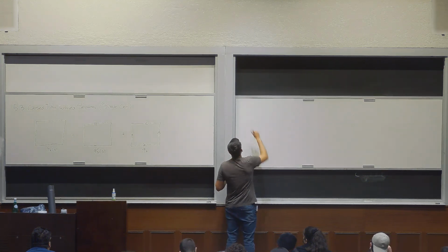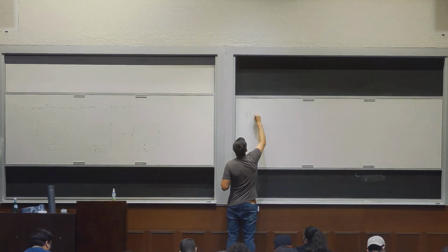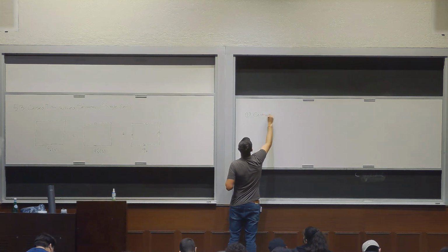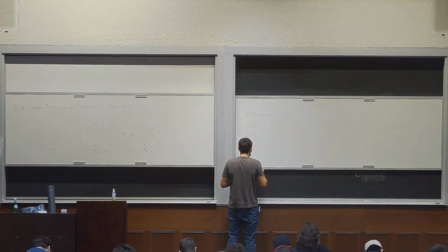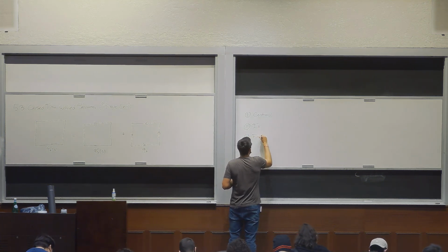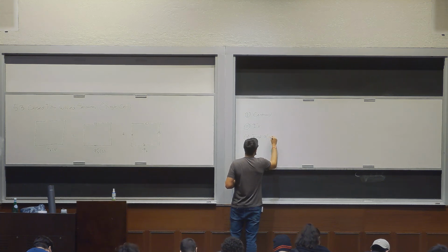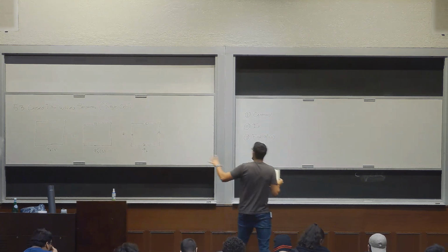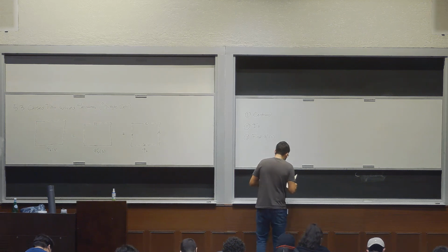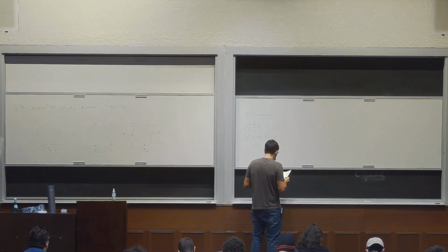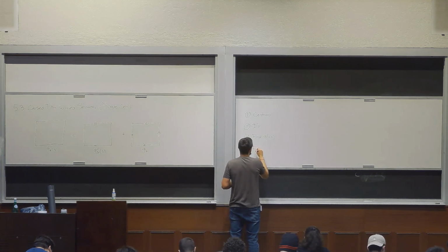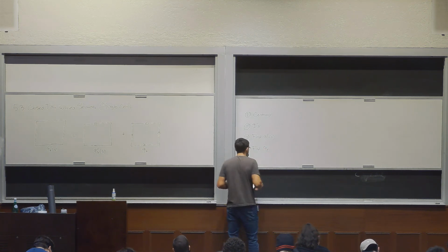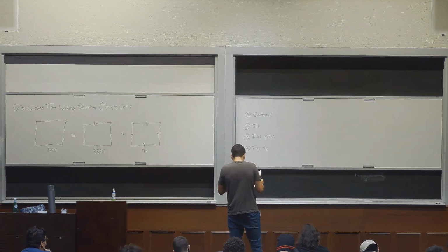So step one, as you can guess, centroid. Step two, I's. Step three, find the Q primes. So make an arbitrary cut, find the Q primes. You could do that. Step four, find Q naught.